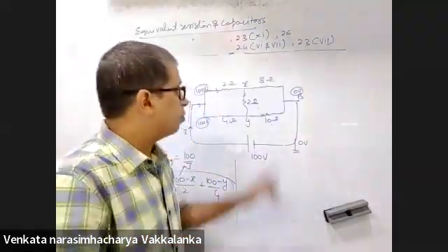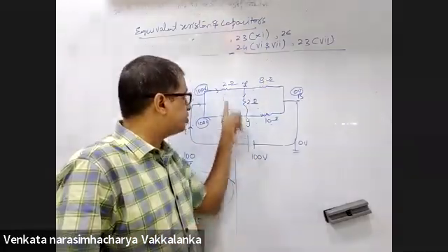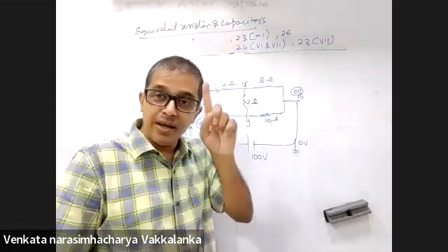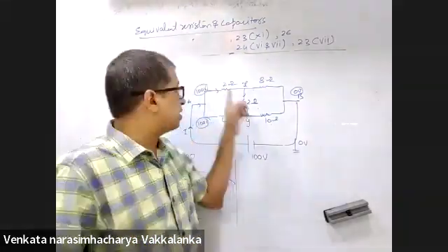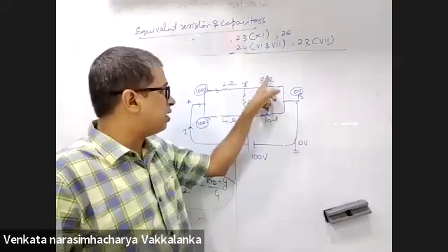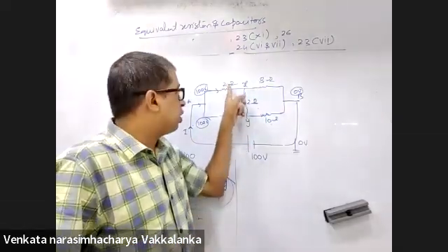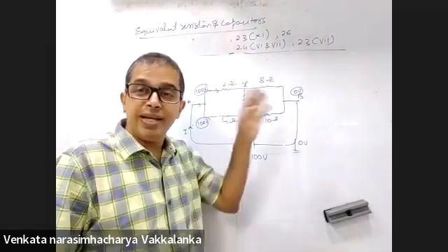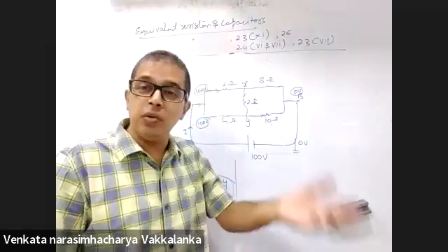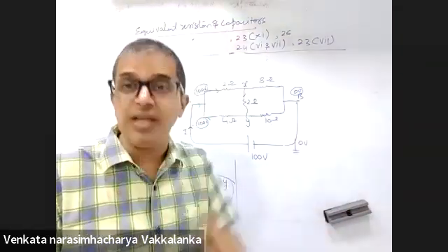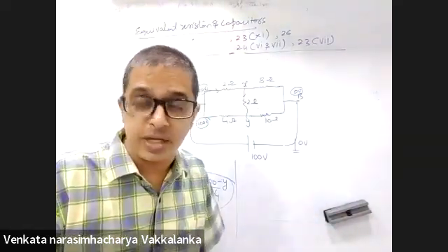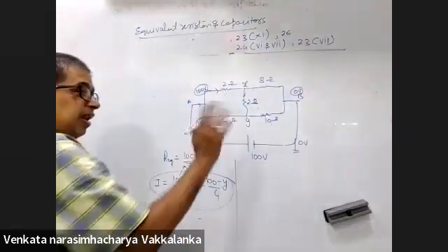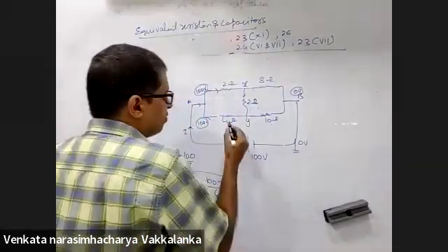Yes, sir. So here I don't have the same resistances here and here. In the example I took in yesterday's class, I took the same resistances here and same resistances here. So I knew that the current here and here are the same. But here the resistances are different. So a new variable comes in. So there will be three equations and three variables if I use Kirchhoff's. Nodal will have only two equations. Please have a look at it.